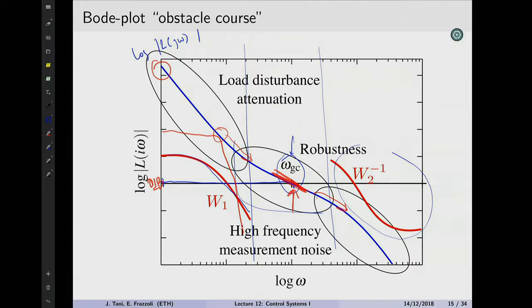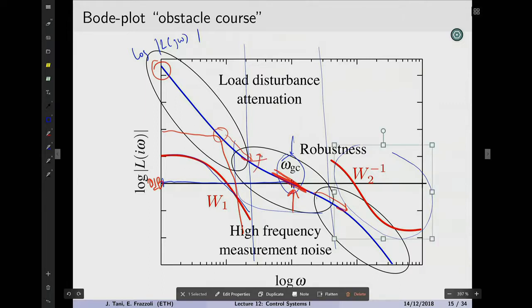And if you remember the lesson on Bode diagrams, we looked at a term at a time. We saw what happens if you got the constants, the S's, the first order terms, and so on. You will remember that if we added a zero in the form of a 1 plus tau S term, we are steering the open loop transfer function up. If we add a pole, we're steering it down. So you can drive your car of the open loop transfer function just adding poles and zeros at the right frequencies.